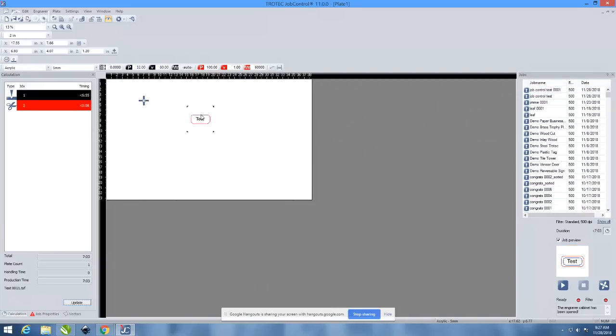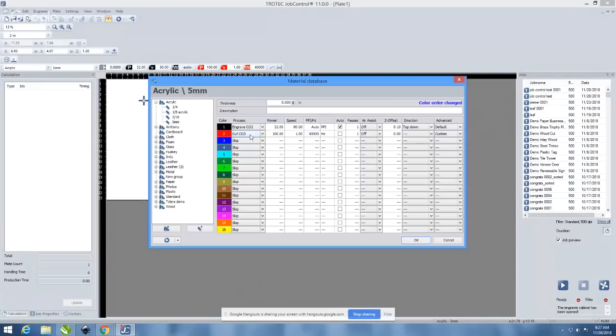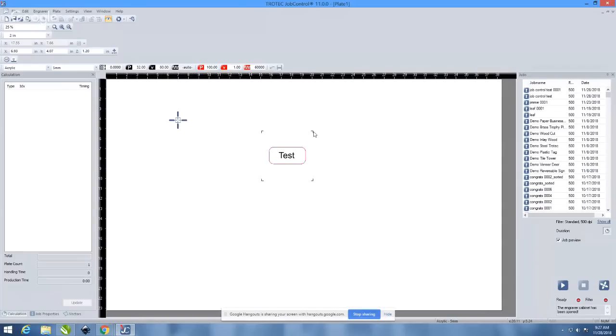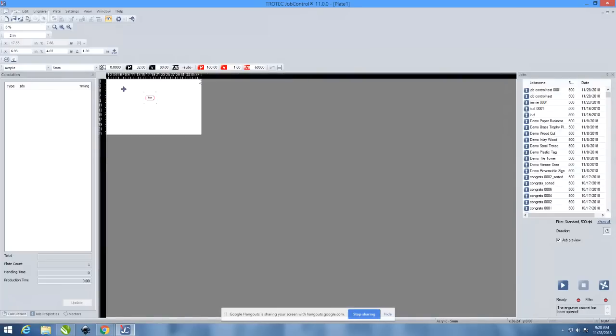Can I just quickly mention for those who are very new and beginners, Anthony, sorry, if you want to go back to that, that white area is a virtual representation of the actual physical table size. So you see it's like 38 and a bit over 23 and a bit. That's the size of the laser. So where you put the job is basically where you have the material on the physical laser bed, just for those who don't know.